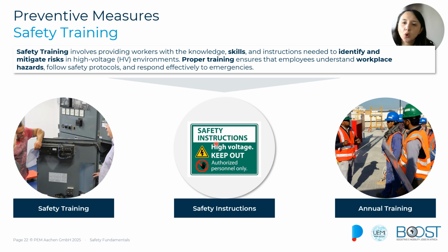Some of the key components of safety treatment are, for instance, to handle and use safety instructions, to have clear, consistent instructions that are tailored to a specific task in the workspace. That is very important. To have, for example, step-by-step guides on how to de-energize high voltage equipment and how to handle, for instance, thermal runaway incidents or fire incidents is going to be very important.